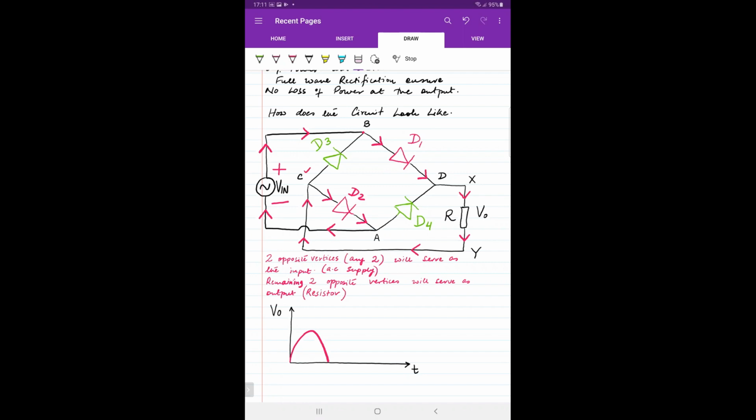Mohit, your wording is also correct. Okay, so for the first half cycle, the two diodes opposite each other have conducted. So in my working, for the first half cycle, the diode D1 and the diode D2 are conducting. Okay, these are the two red ones whose alignment was identical. So these two are conducting for now.